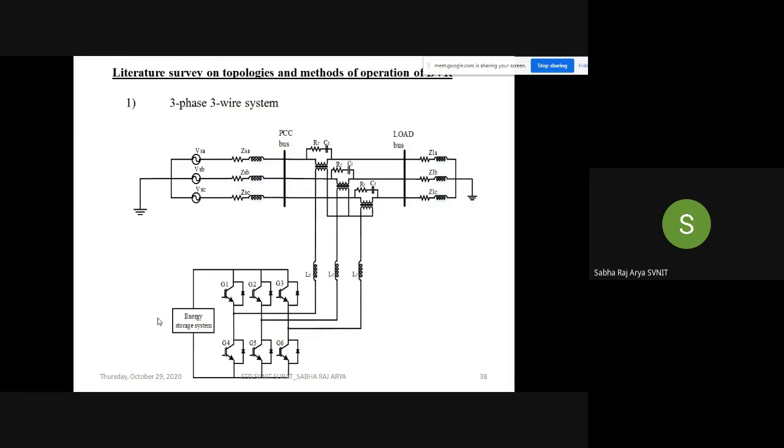Assume that this system may be of two types. One is based on the energy source, the other based on the DC link. With the DC link, you are going to generate the compensating voltage coordinated with the line current. But in the energy based system, you are going to generate the compensating voltage in phase with the voltage. In this case, we want to maintain the rated voltage at the load terminal, not the supply terminal. The supply we are not going to correct.